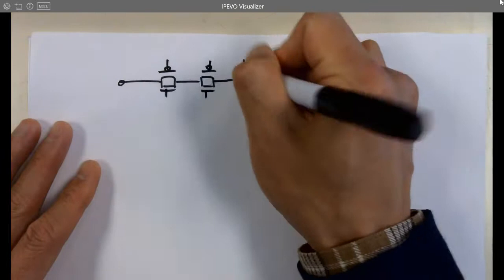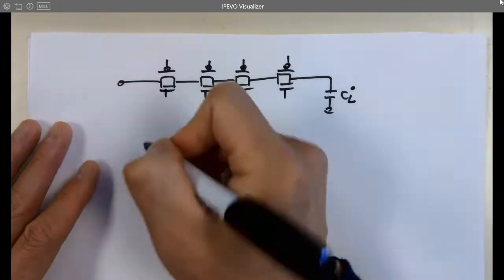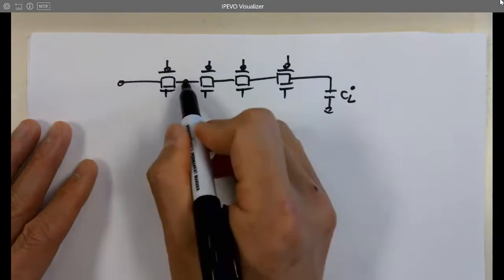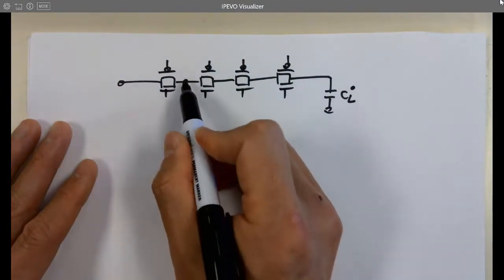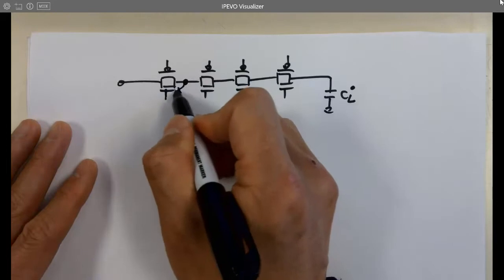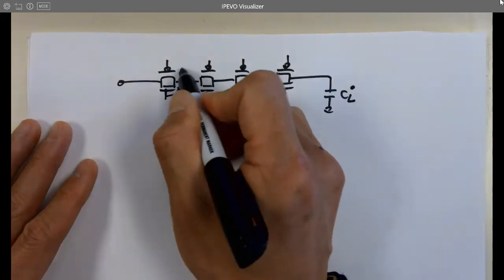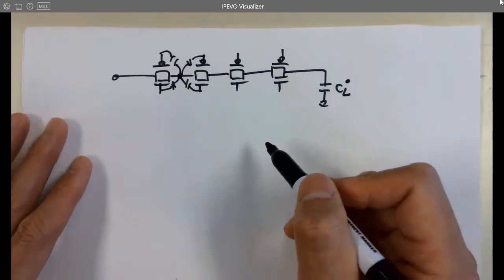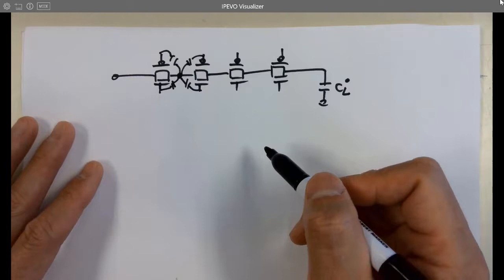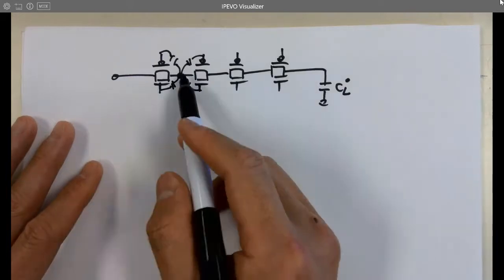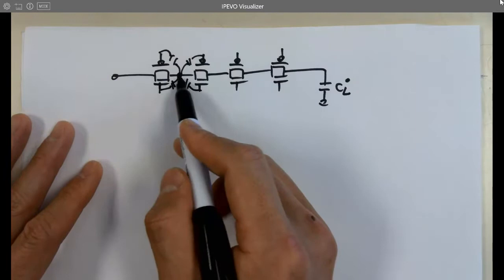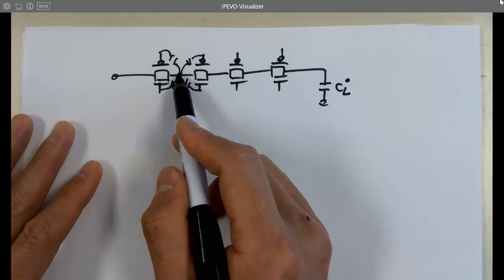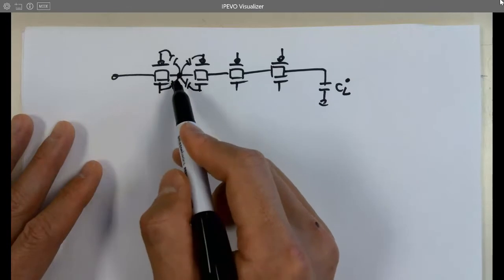This is transmission gates. How to model it? Calculate the time delays. So if you look at the point here, what's the time delay at here? So we have 1 cap here, 1 cap here, 1 cap here, and 1 cap here. So you have mirror effect? No, there's no mirror effect. It's a transmission gate. Charging, discharging. The other side doesn't have a power connection. No VDD, no ground. So it's just either charging up or discharging.